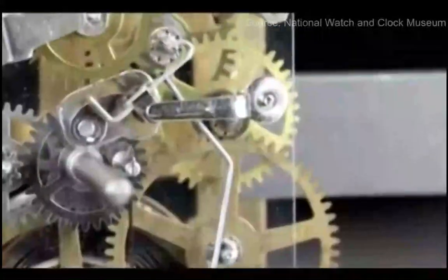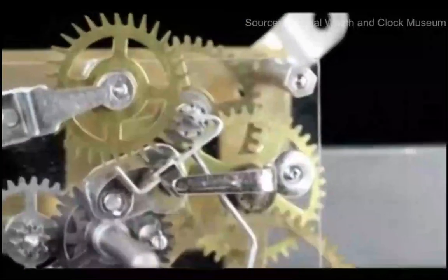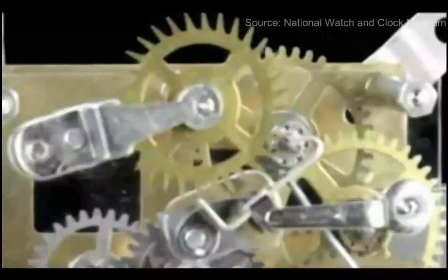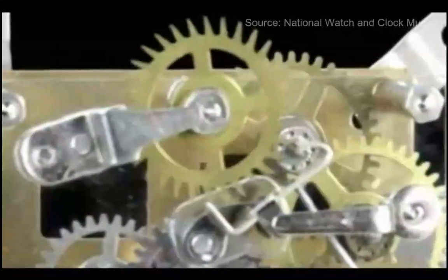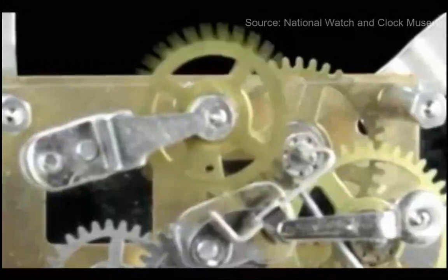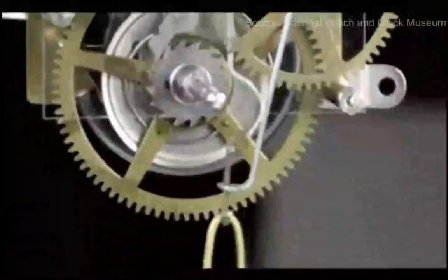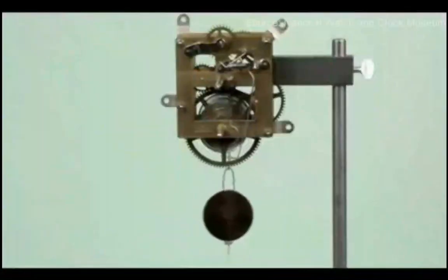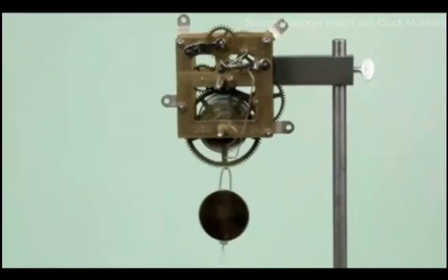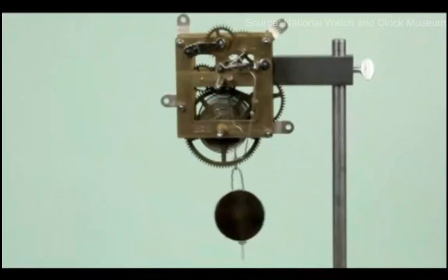And in order to channel this abundance of energy, an escapement mechanism is incorporated to slowly utilize the energy in small portions. The anchor visible on screen moves the escape wheel in contact by just one tooth each time. The timing of the escape wheel, and effectively the entire clock, is dictated by the oscillation of the pendulum, which is perhaps the most vital element in the entire instrument.